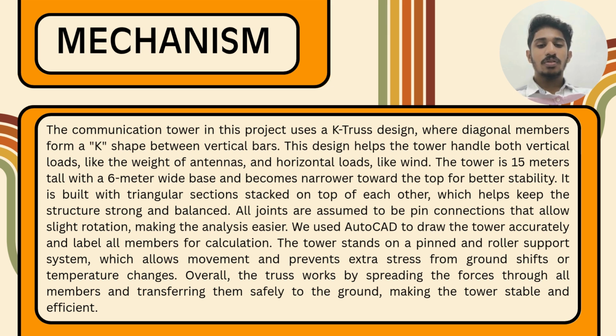The tower stands on a pin and roller support system, which allows movement and prevents extra stress from ground shifts or temperature changes. Overall, the truss works by spreading the forces through all members and transferring them safely to the ground, making the tower stable and efficient.